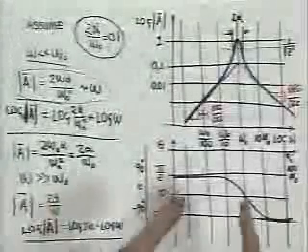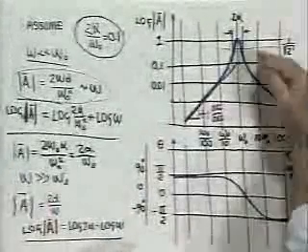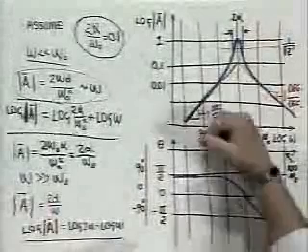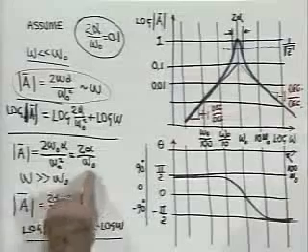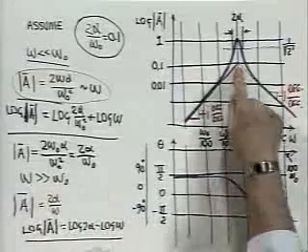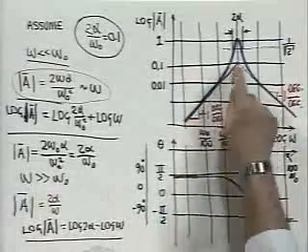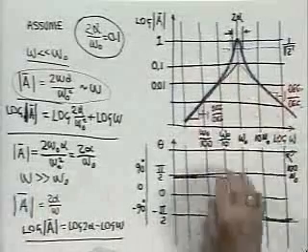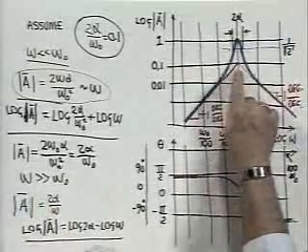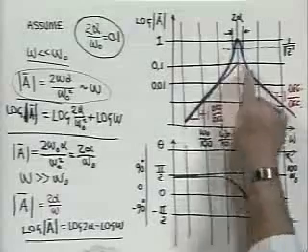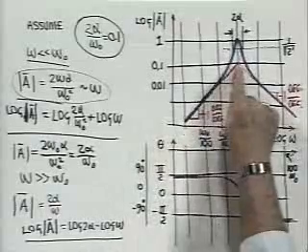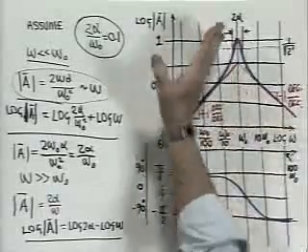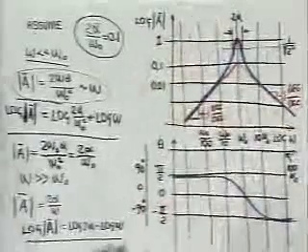And then in order to route those asymptotes somewhere, to find out where they go parallel to themselves, you evaluate what the asymptote would be at omega naught. That gives you a point on this graph, and you draw it with the right slope from that point. The asymptote does not describe the function at that point, as you see, but this procedure gives you a basis for nailing where, parallel to itself, the asymptote belongs.